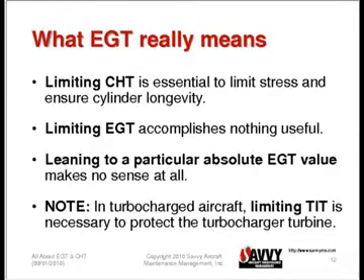What does the increased EGT mean? It means the engine isn't converting as much energy from the fuel into power as it's supposed to, and more of it is getting wasted out the exhaust. That's why EGT goes up. So trying to keep EGTs below some value not only doesn't make any sense, but it's kind of counterproductive.